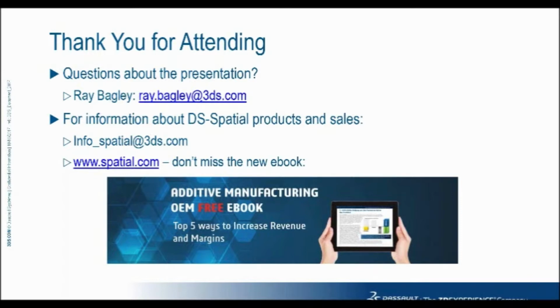Yeah, that's interesting. That's certainly a high degree of confidence if you can do that. For those coming from the subtractive world, say 5-axis machining, you still think in terms of tolerances, but the general assumption was that if you're going to G-code and you could get as much as an order of magnitude more precise at the design level, then any tolerances or error at the design level just disappear into the G-code, because you're so much better than the machine's capability. I'm just wondering, in this case, if we're at a point where we can design so much better than the machine can produce, should a designer perhaps worry less about precision and repeatability given the capability of their machine? Does that make any sense?